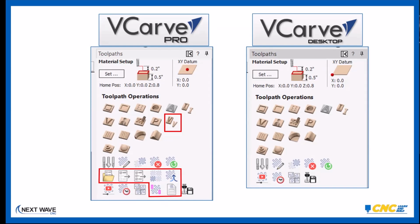And so what I was saying is that there was a little pink corner right here. This is called a setting which will prevent the tool from running in certain areas of your program, so that if you have a clamp, you can block out that area with a vector rectangle, select that, and then when you run your toolpath, your tool bit will actually run around that area and avoid running into it. Again, it's pretty handy, but with some careful layout, you don't necessarily need that either.